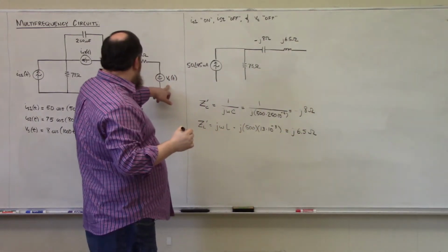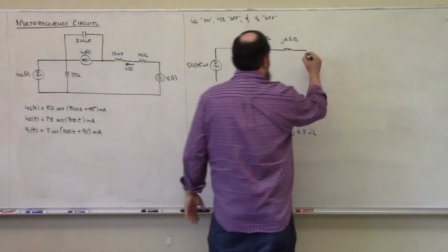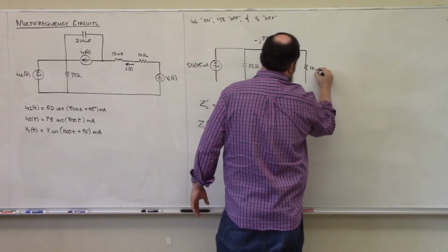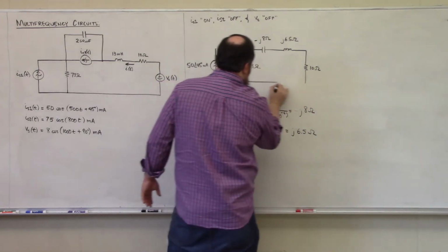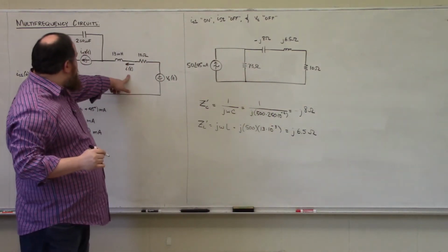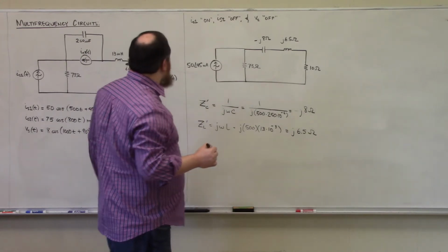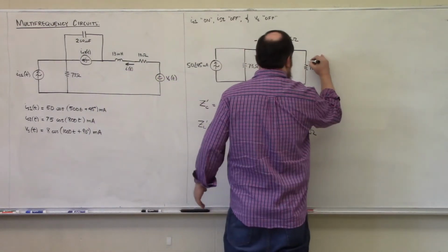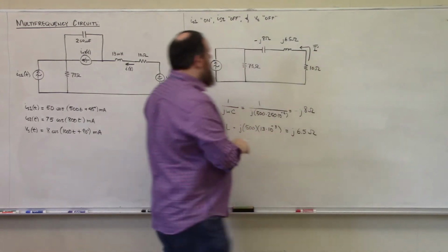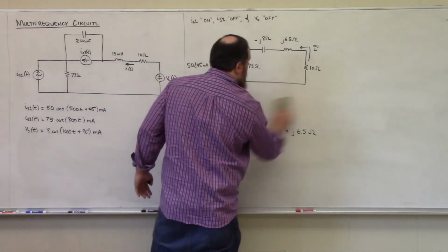My voltage source is going to be a short circuit, so I'm just going to slide this 10 ohm resistor down into this spot to just make things look a little prettier, in my opinion. And the phasor representation of this current i of t will be a phasor current I that's flowing from the 10 ohm resistor to the 13 millihenry inductor. So this is our phasor current I prime.